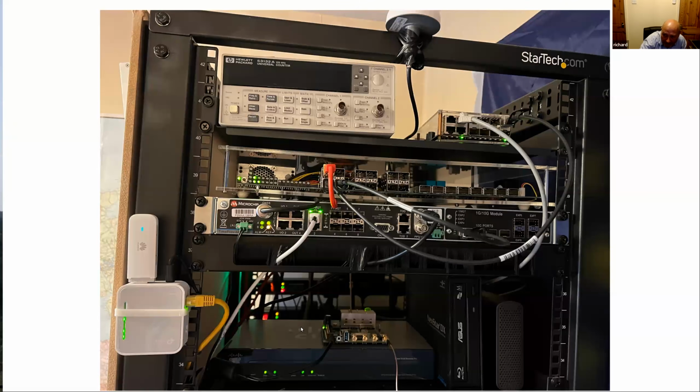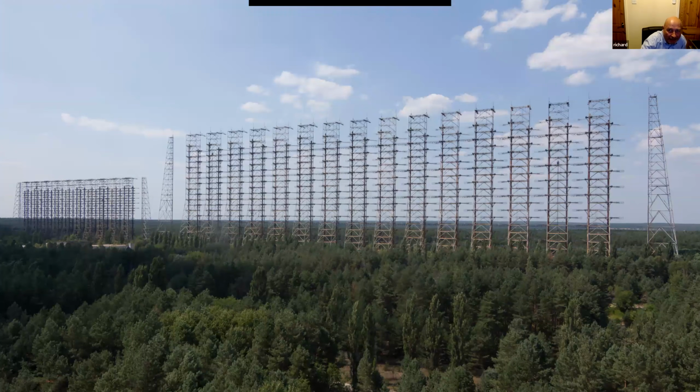And so I've got network jitter at the moment down to about 1 nanosecond between the two 19-inch devices running precision time protocol and synchronous Ethernet, and I'm hoping to get the same results from the other boards as well. But I just wanted to do that before I closed it down. But yeah, very interested to find out a little bit more about what you're doing.